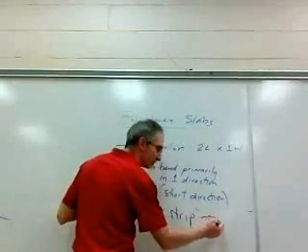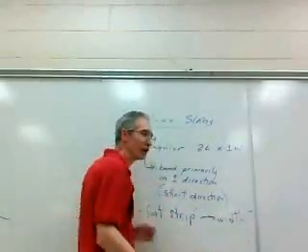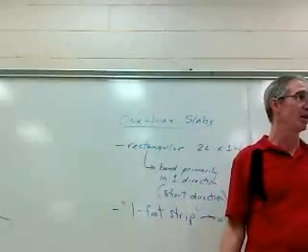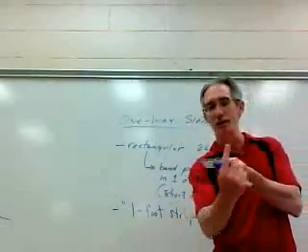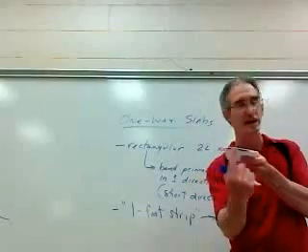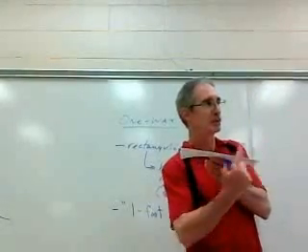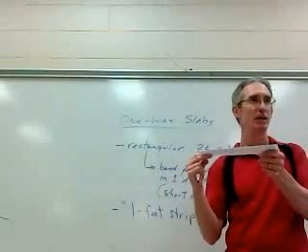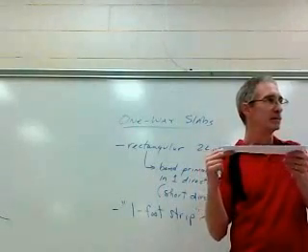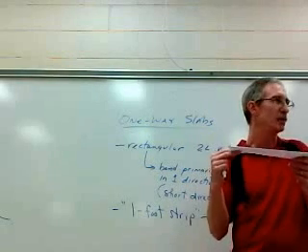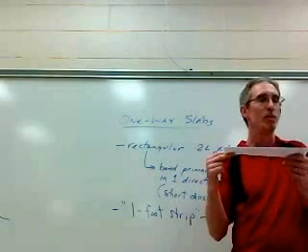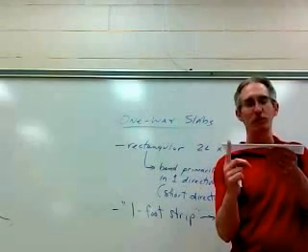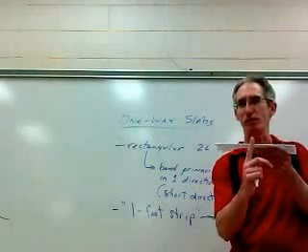That'll be your width. So, you know, you could look at a slab and you could say, hey, my slab's 20 feet wide. I mean, the slab might only have a span length of 5 feet, but the slab might be 20 feet wide. Well, should I evaluate it like it's 20 feet wide? Well, you could. There's nothing wrong with that. Your numbers probably get pretty big. What most people do is they say, well, this 1 foot strip from here to here is the same as this 1 foot strip from there to there.